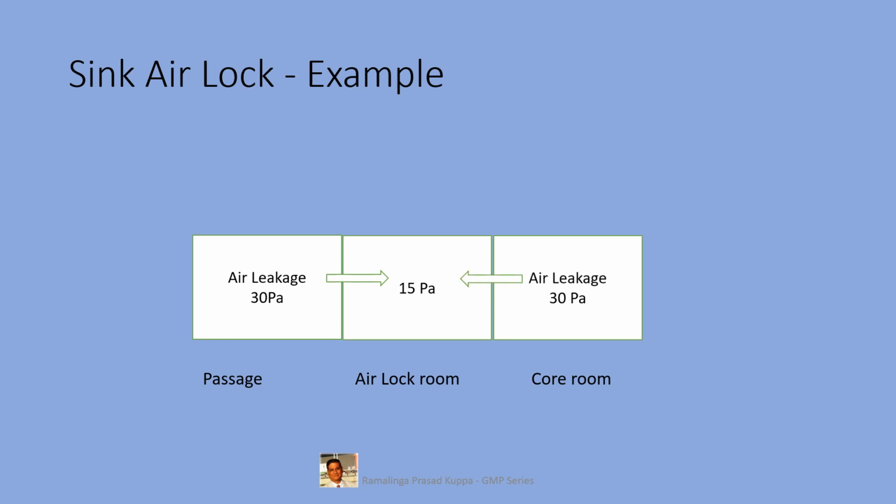This design would suit for high potent drugs which may contaminate the passage in the Cascade airlock system. In this design, the passage is protected and the contamination is contained within the airlock. The airlock can be cleaned individually once the process is complete. Same principle for opening the doors. Opens to the positive pressure side.